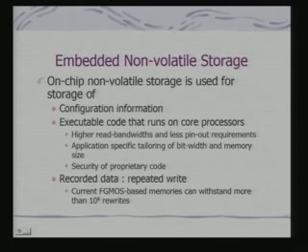Current FGMOS based memories can withstand more than 10 to the power 6 rewrites, and another observation is that once charged, the charge leakage time can be as large as 10 years. So that's why for recorded data, when you have a speech recorder or a camera, you actually have these flash cards or the flash memory to store the recorded data.